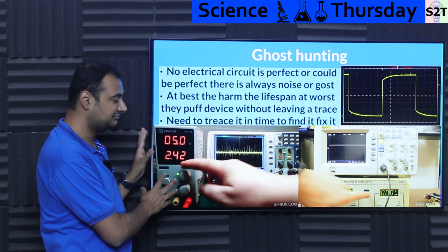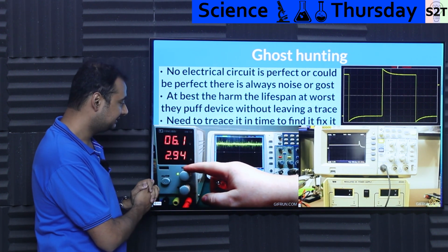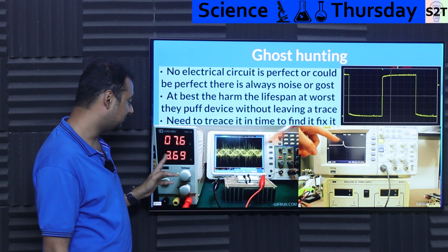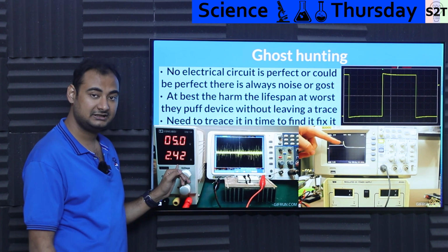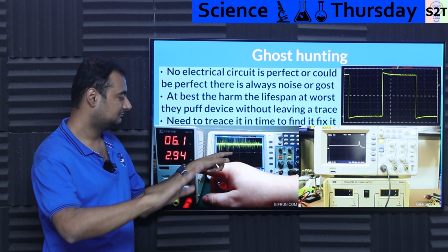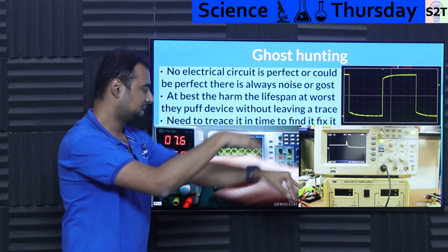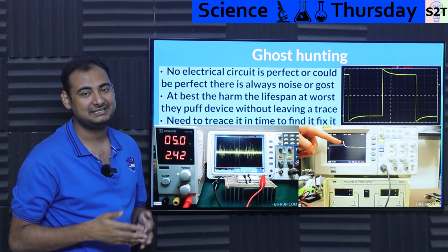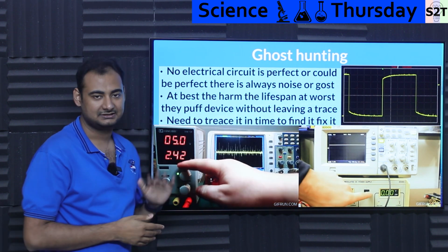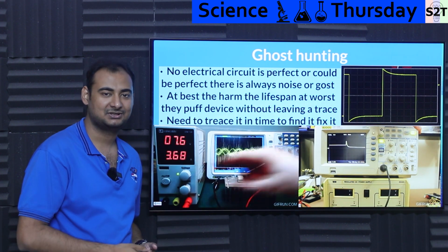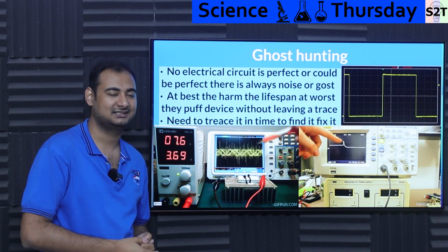Like this is an example of a Chinesium power supply, and you can see that this power supply claims a 10 amp power rating. Here's the deal, this individual only loaded it up with a power resistor to 3 amps, and you can see that it's slowly becoming like this. What the hell? Basically, it's oscillating. It's not able to sustain it properly. This is the difference between a Chinesium power supply that is like for 5 rupees, for $1 we can give 1 kilowatt of power. It's like, no, you can't.